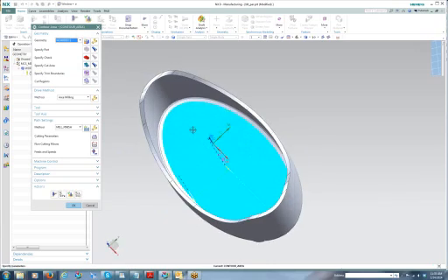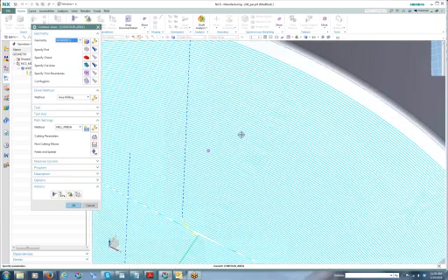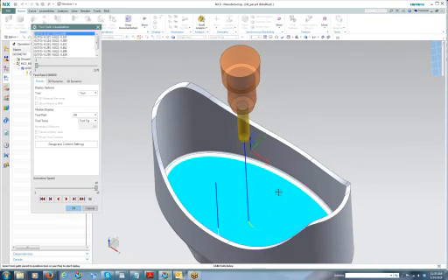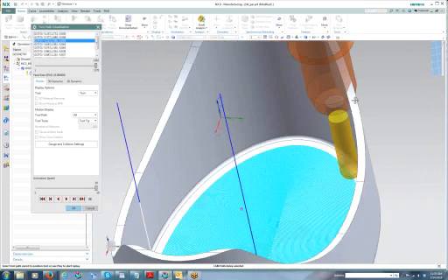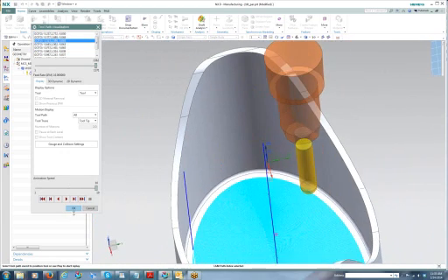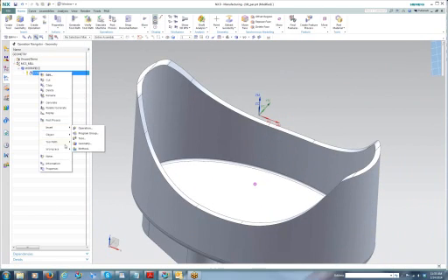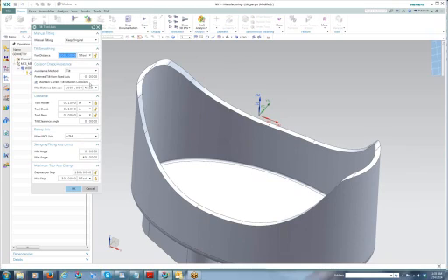Okay, so what we have now is a toolpath that's just spiraling around to finish the cavity. It's a very easy to create toolpath, but of course as we get towards the outside, you can see that the holder of the tool crashes on the tall vertical walls. Let's now right-click, choose toolpath and tilt tool axis, and we'll just give it a maximum angle here of 20 degrees.